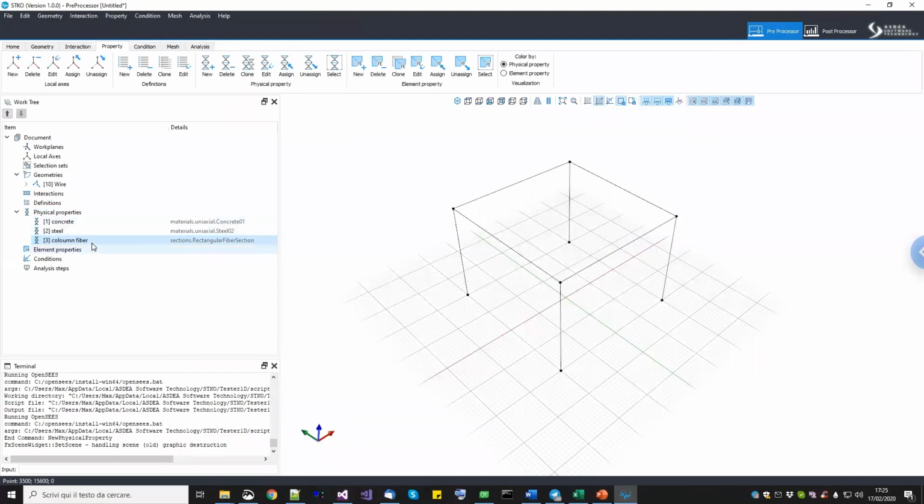We are not going to add directly the fiber cross-section to the elements because we need one extra step. Typically, when you do a solid model, it is fine to take a material and drag and drop it to the geometry. But for a beam, it is a little bit different. You don't need only a material. You also need the integration scheme, because in OpenSees you have many integration schemes for the beam. So that's why we need this extra step.